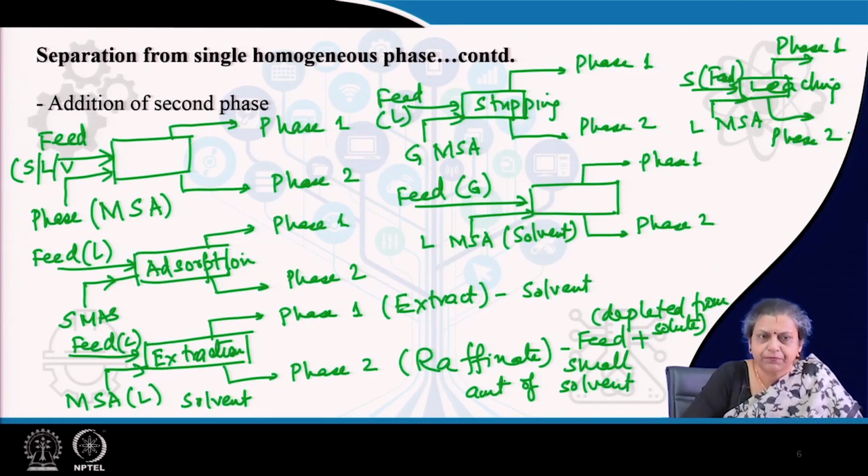and this process is known as stripping. Removal of water vapor from air, that is, drying of air, is a very well known adsorption process. Then dissolution of carbon dioxide from a carbon dioxide air mixture by the addition of amines or water is a very standard, well known absorption process.